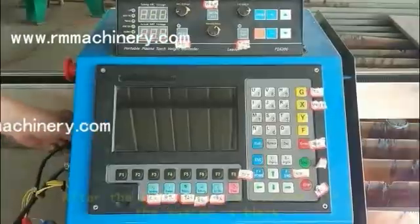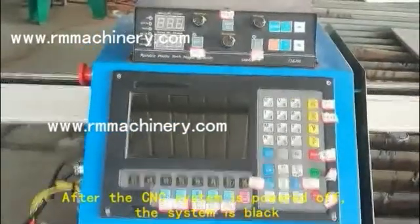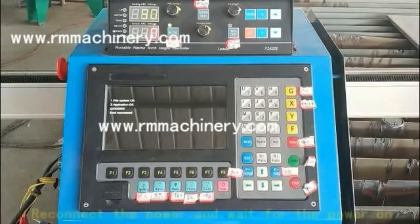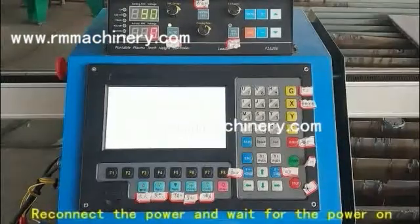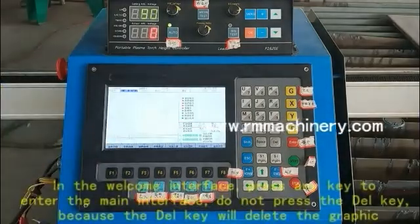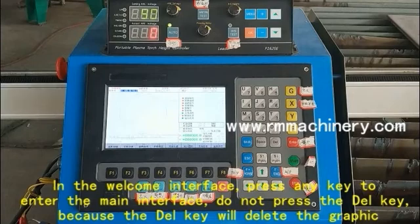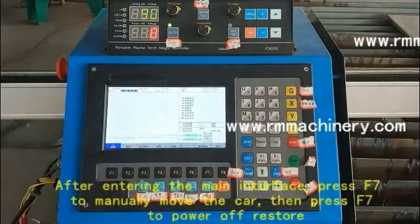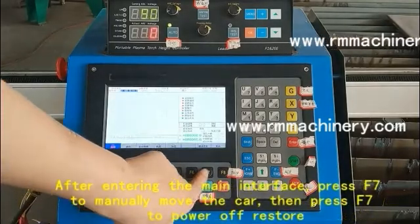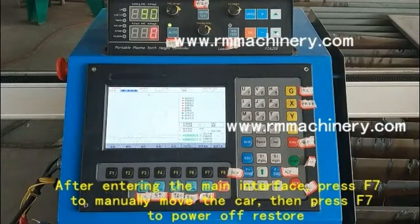After the CNC system is powered off, the system is black. Reconnect the power and wait for it to power on. In the welcome interface, press any key to enter the main interface. Do not press the delete key, because the delete key will delete the graphic. After entering the main interface, press F7 to manually move the car, then press F7 to restore after power off.